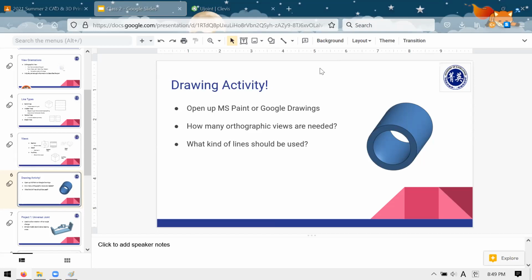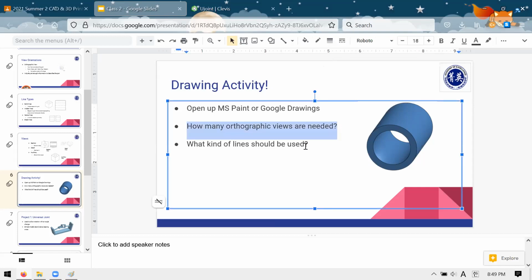Yeah, I'd agree with you there as well. Seems to me that with 2 views that are perpendicular to each other, you get all the information, since if you include more than 2 views, you end up with at least 2 views that are the same as each other, right? Like the front and the back of this tube are going to look exactly the same. Likewise, the top, bottom, left, and right are going to look the same as well, assuming that we're treating the circular face as the front. So good work with that part.